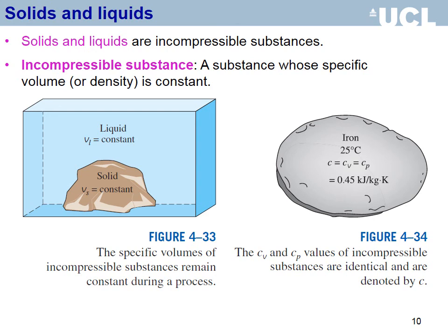Okay, so these are not gases. So it's not that Cp is equal to Cv plus R, as for an ideal gas and so forth. For incompressible substances, Cp and Cv are equal to one another. That's why in high school, when we learn about specific heat, we don't bother talking about two different specific heats, because we have not studied thermodynamics until that point, right? So for liquids and solids, to a very good approximation, there is only one specific heat, and that's equal to Cv and Cp because they are both one and the same for incompressible substances, which are solids and lots of liquids.